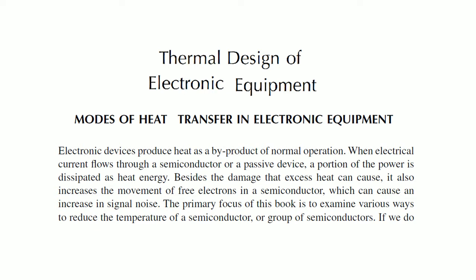It has, in the on condition, a small voltage and a large current, and in the off condition, a large voltage and a small leakage current. In spite of the best switching transistors, the best switching semiconductor devices, there is a rate of switching, how quickly it turns off and on. That little period required for it leads to heating.